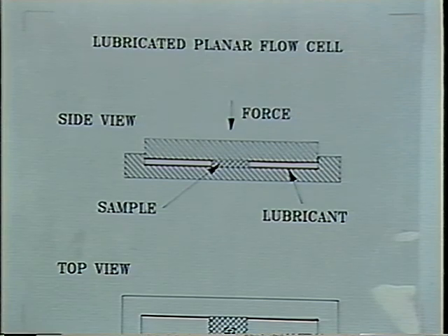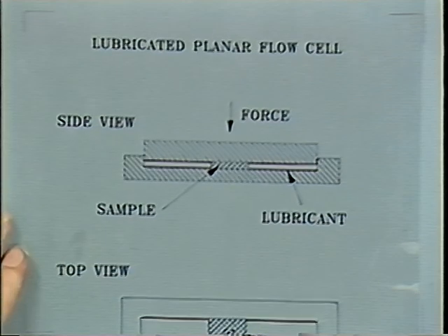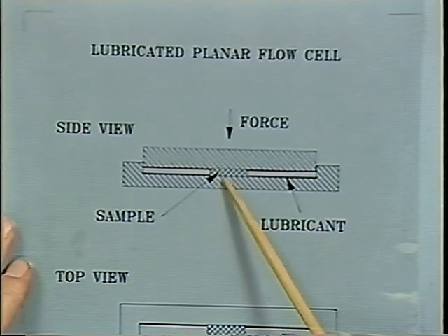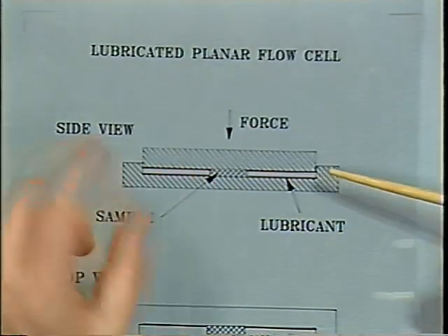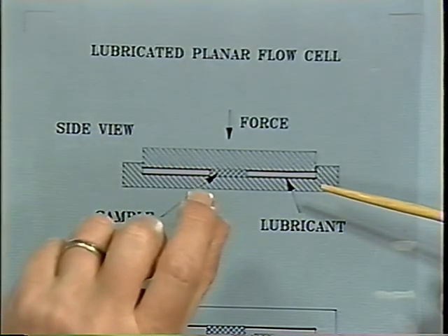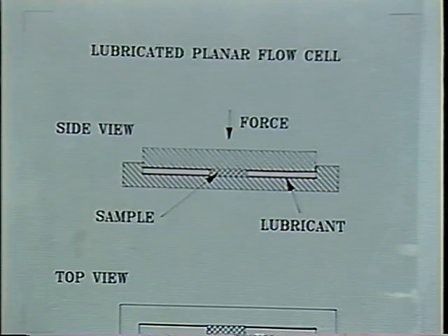We wanted to use different techniques which would give us large samples of highly ordered morphology. For that case, we applied planar extension. That's a deformation where the sample is extended in this direction, held constant in the second direction, and shrinking in from the top and the bottom.